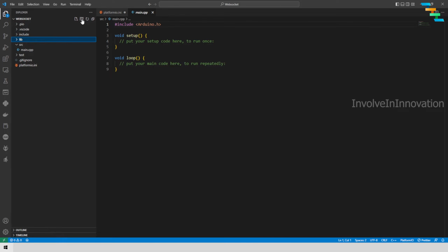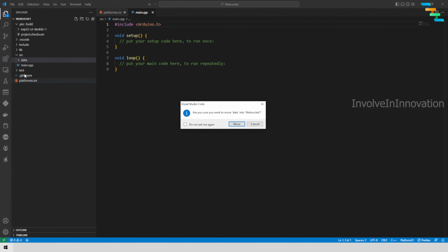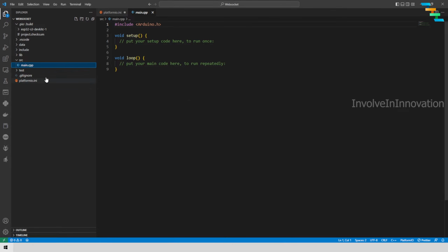We need these HTML, CSS and JavaScript files because these are the files which will be supplied from our web server. Here our web server is nothing but the ESP32. Whenever a client connects to the server and goes through the route, it will get the HTML page which has the 3 checkboxes. This will be provided by your web server.